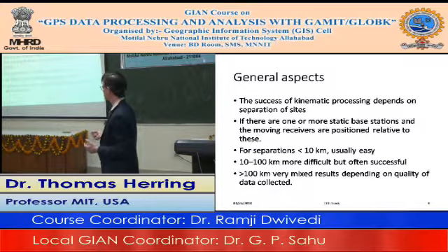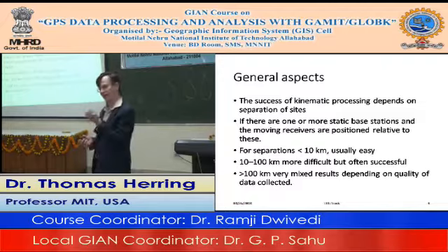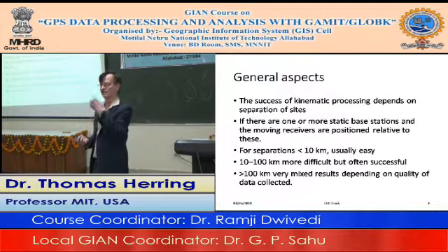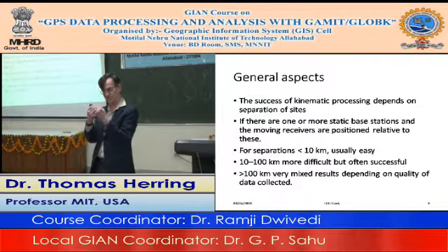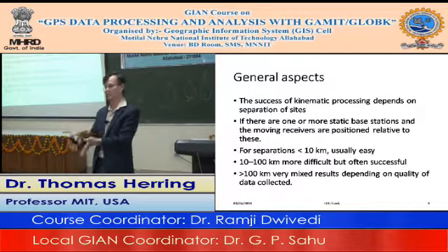10 to 100 kilometers, often you start then needing to do a little tuning. And that tuning is associated with essentially how active is the ionosphere on the day that you are processing, and how good is the data collection. One of the surprising things I have found with kinematic data is that the receivers, when they're sampling, say, at 10 hertz, often don't actually record all the data they've collected. And so in the kinematic processing, it looks like there's a gap in the data, but there really isn't. It's just that it never recorded it.